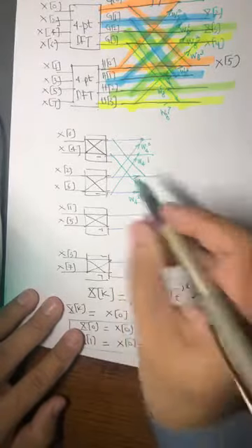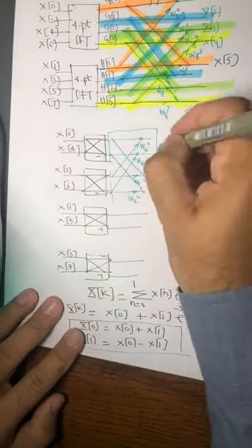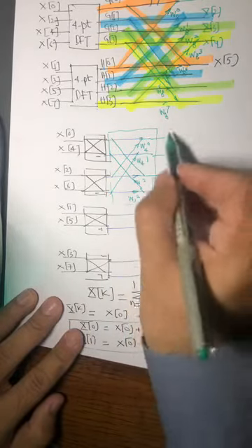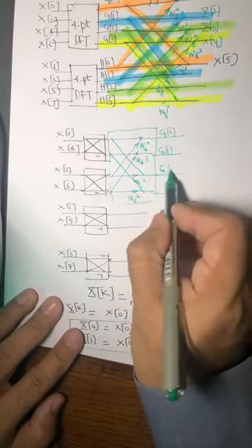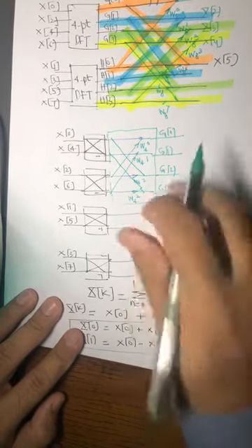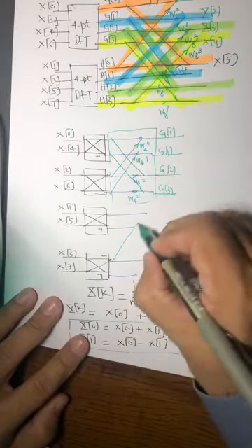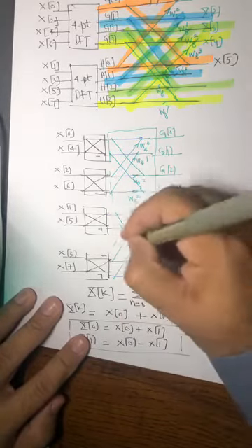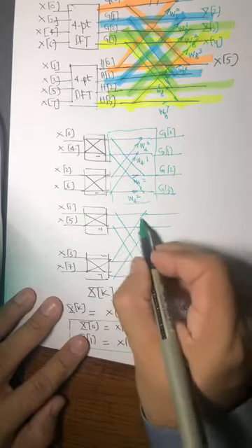So this is the box which we earlier marked as 4-point DFT. So you get 4 points of G0, G1, G2, G3. So we were calling this G0, G1, the same, G2 and G3, and now we can combine them together. And similarly here, you combine this, and you do this, and this. So butterfly, butterfly, butterfly, butterfly, so many butterflies.